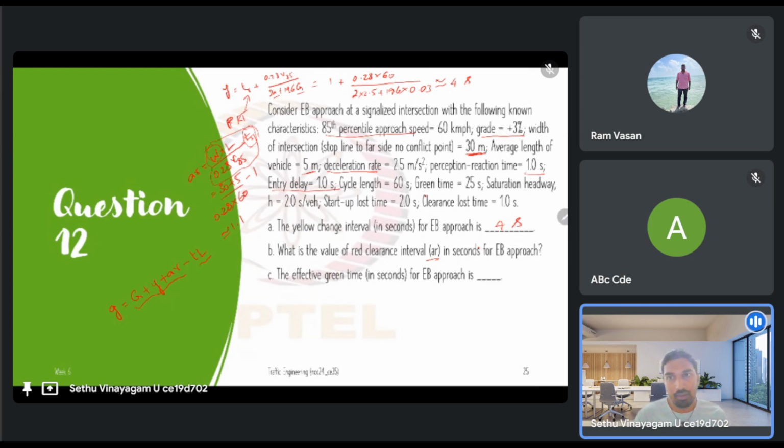In the green time, the change interval and the all red interval, vehicle movement can happen, but the total loss time is where vehicle movement does not happen even though it could have happened. The total loss time can also be split up into the startup loss time and the clearance loss time, L1 and L2.